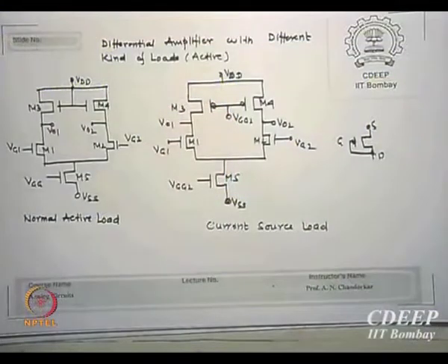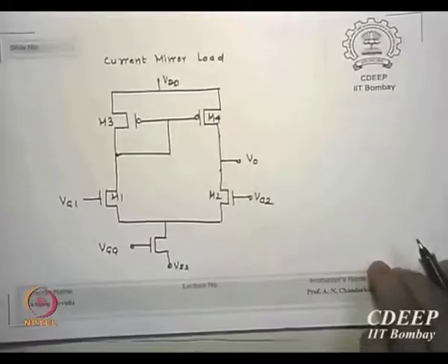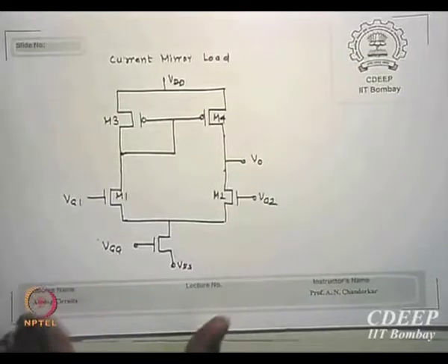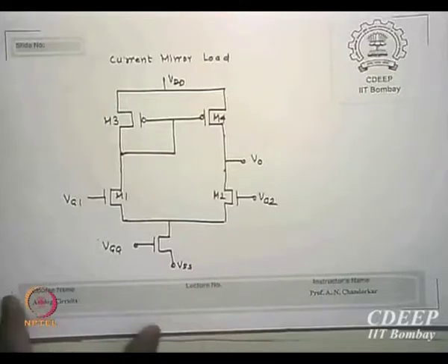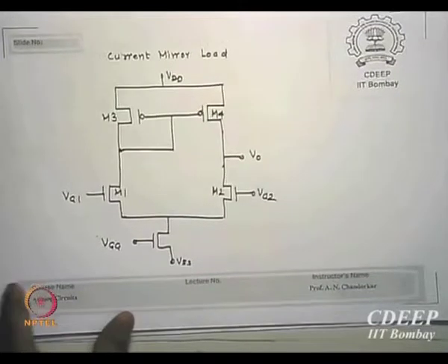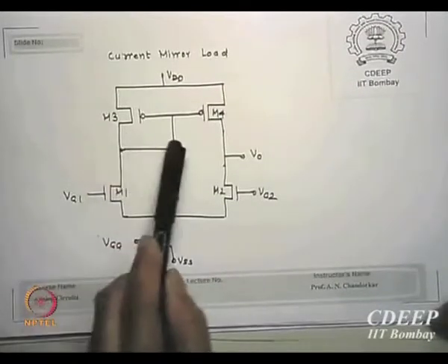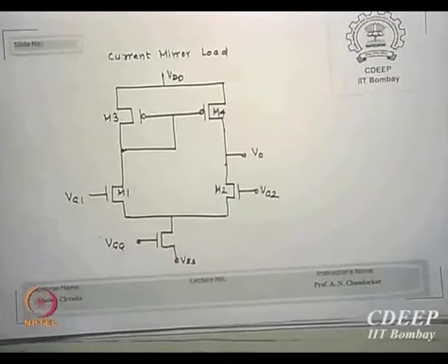Okay, what will the third be? Diode connected is done, current source is done. This is called current mirror load. This is the connection which all analog op-amps will use. This is the kind of load all op-amps use. Is this connection clear to you? The gate is connected to only one side of the drain.